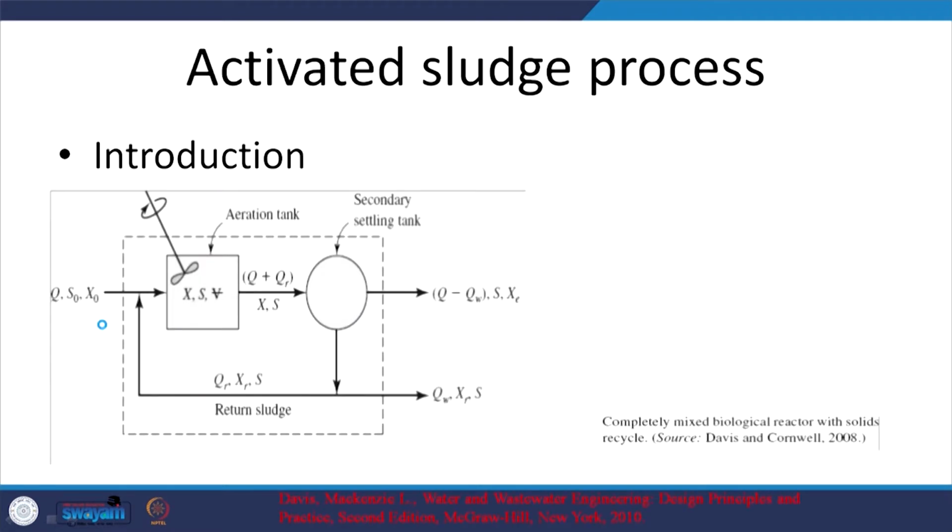So, the activated sludge process. Again, why do we call that activated sludge? Let us understand that. I do have a relevant schematic here, we will come back to that. My wastewater is coming in, this is after the primary sedimentation. What does it have? It has a lot of organic content, which I am going to call substrate, which is my waste and the food for the relevant microbes. But the concentration of the microbes in this sewage or wastewater, which I am going to represent by X, is going to be less. There are going to be some, but not enough for fast degradation, and the kind of microbes that are present might not lead to the degradation that we are looking for.